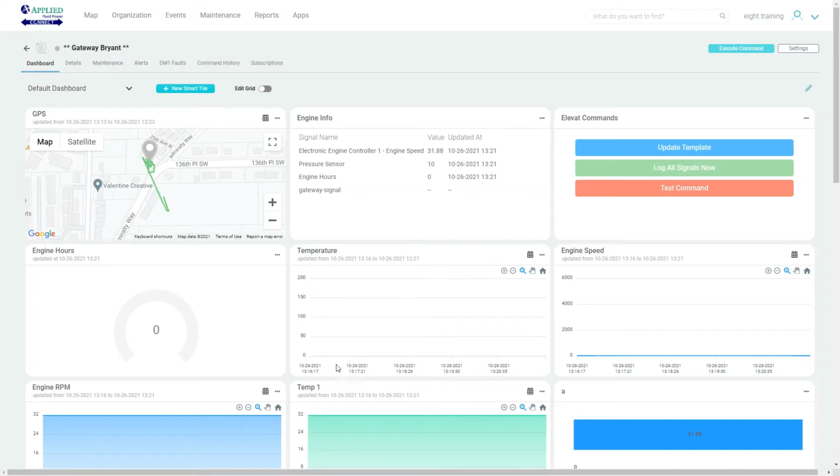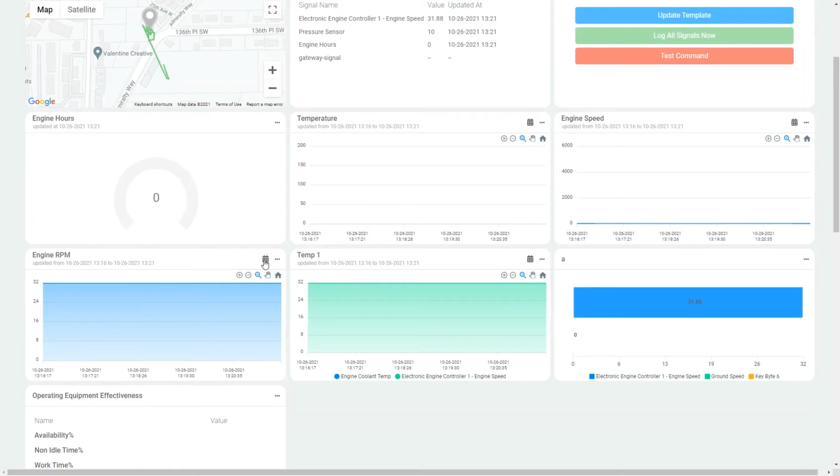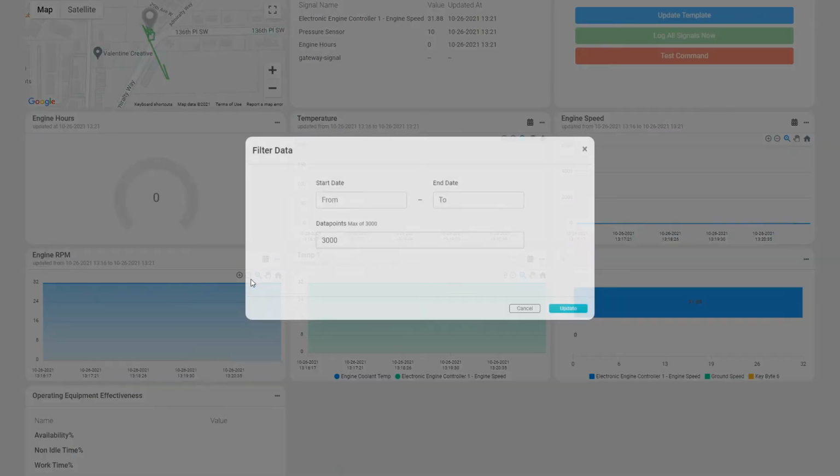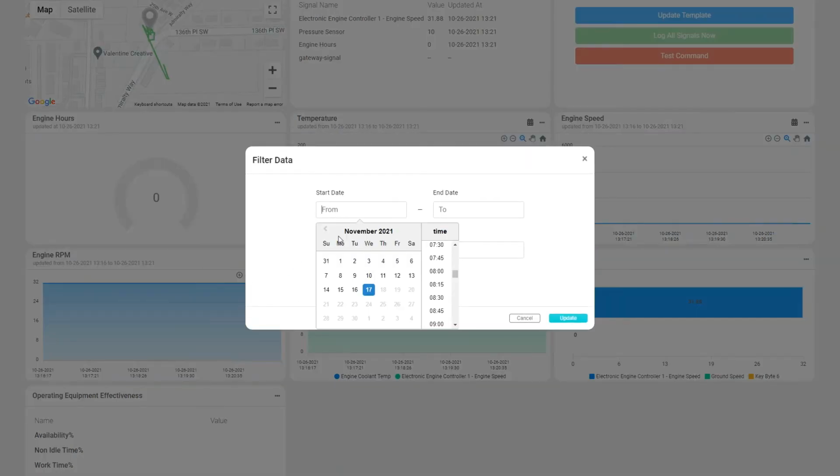Now the other thing I did want to show you here is we can historically go and look through our little calendar icon that we have here, and we can look at the last 1 hour, 3 hours, or 8 hours by default. We can look at information that's happened over those times. Otherwise, we can come in here into this custom area, and ever since the machine was first commissioned, we can go back and look at whatever date range that we would like. So here again, this is just accessing all the information back in the database. Very powerful to be able to go back and troubleshoot what was happening to a machine a couple days ago, a couple weeks ago, or even a couple months ago.